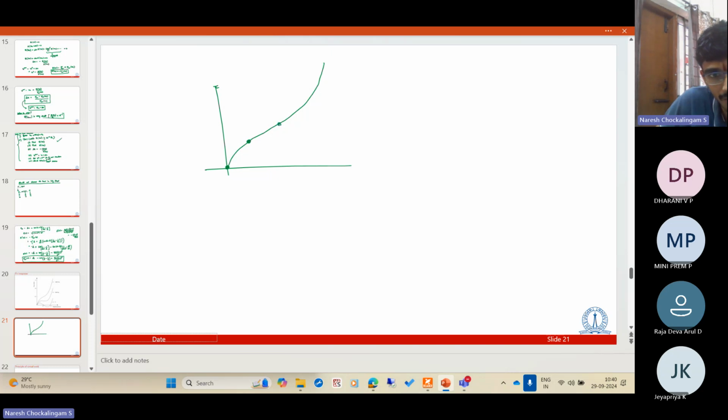So I'm increasing force in these steps. At this force value, I know the force and I want to find the displacement. So I want to start with an initial guess. I use Newton-Raphson, so I need an initial guess. I'll hit this force, find the residual, hit that, find the residual again, and slowly converge to this point.